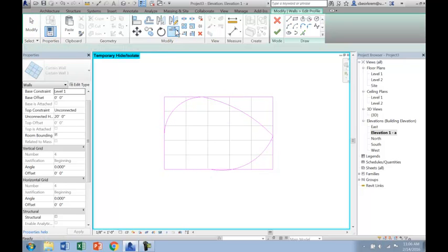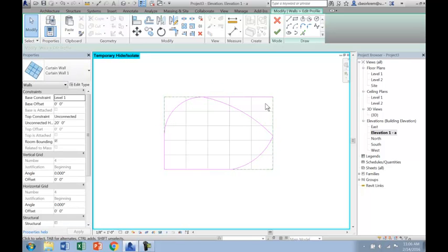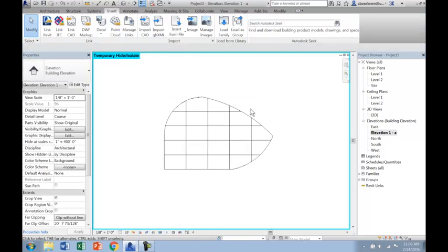Now, as I was talking about at the end of the day with the diagonal cut across the gallery in Center City, you have to make sure that this profile is still complete. So I'm going to go through and use Trim Extend to get rid of some of these elements going around. And I'm going to trim that guy. And then I need to come in and just delete these. So again, the point is that you have a complete profile that's clean and finished, and it's going to give you an error if you don't.